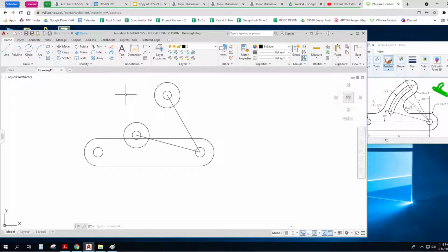I can do an arc command. Okay, but there's a few other things I want to do. So I know that there's an arc from where this little intersection is down somewhere over here. I don't know where. And then I'm going to fillet it. And same with this one. So I'd like to lengthen this thing out. So I'm just going to draw another line out along there.